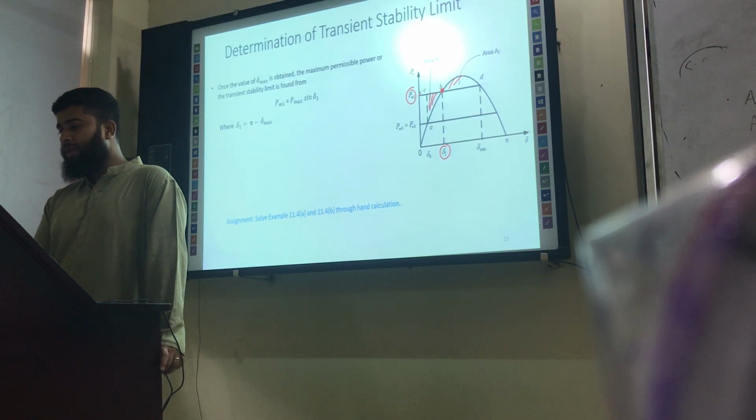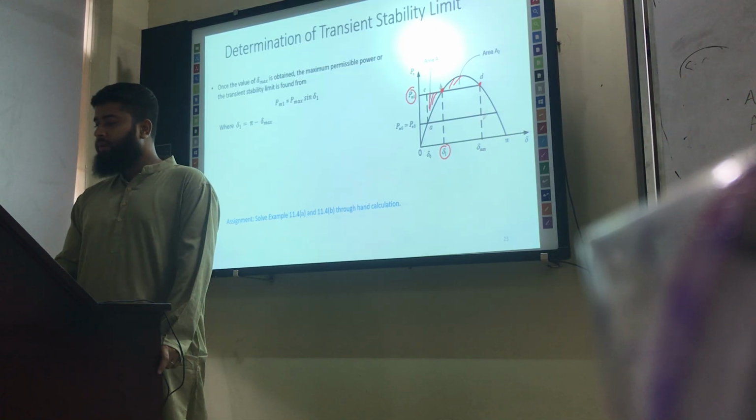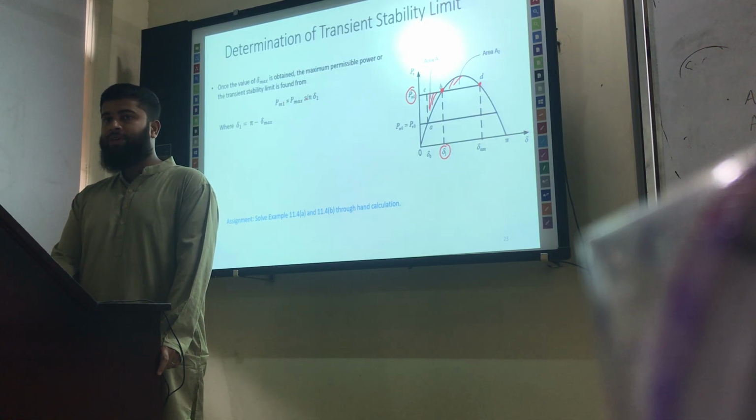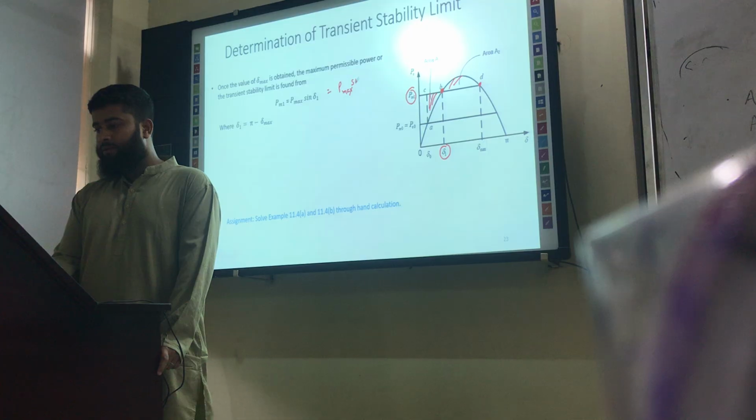Also we can take PM1 as the P value of this point, that is P max sine delta max. So we can take either expression. Here we have taken PM1 as P max sine delta 1. Also this can be equal to P max sine delta max.